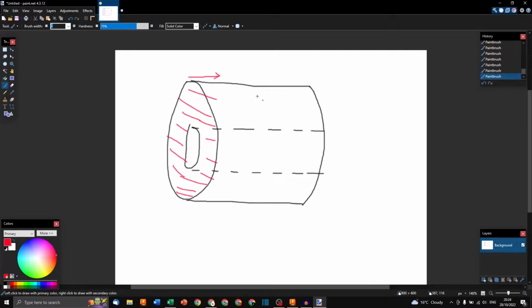This object we call 2.5D because it's a 2D object that's the same on every single plane. Typically this is ideal for 3D printing because the printer adds layer after layer after layer. So if you flip the wheel up, you could print it from the bottom up. So, a sketch. Next thing we need to know is the concept of an origin.